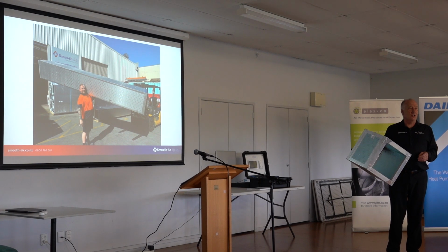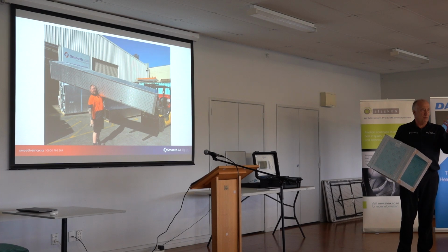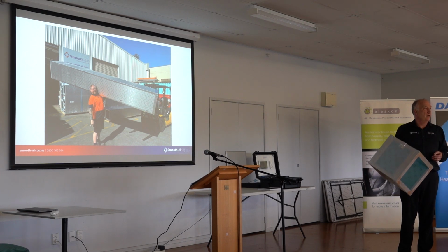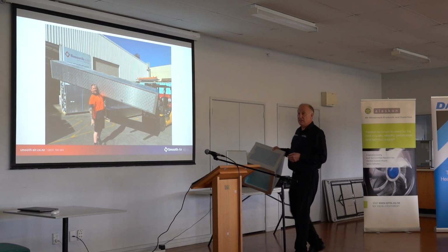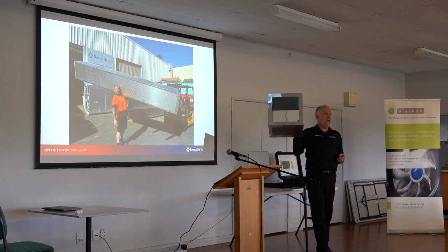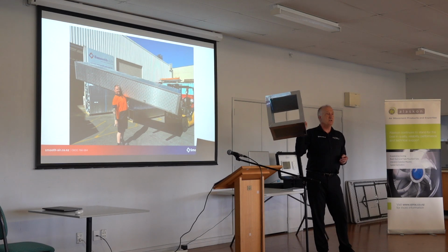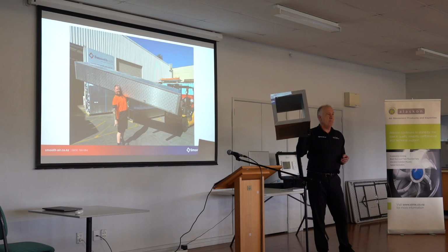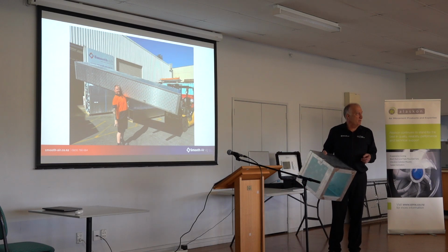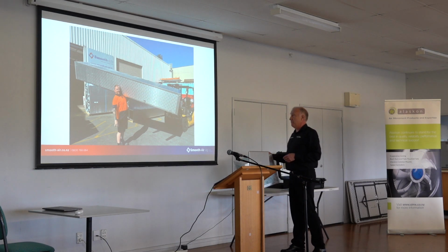So all your installation issues in terms of weight, freight, health and safety, all the gripples to hold it and seismic bracing and all that stuff is reduced to an eighth if you were using galv duct. Massive savings. Cost to build that compared to an insulated galv duct is about the same. So material costs about the same, cost to install way down. A much better solution than wrapping galv duct. I say that with my tongue in my cheek because as a company we make quite a lot of money out of wrapping galv duct, but I think that's probably a better product.